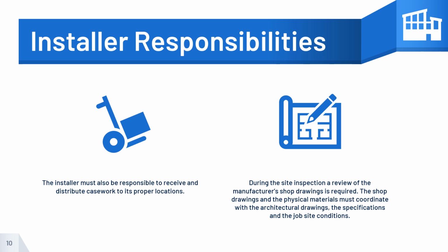The installer must also be responsible to receive and distribute casework to its proper locations. During the site inspection, a review of the manufacturer's shop drawings is required. The shop drawings and the physical materials must coordinate with the architectural drawings, the specifications, and the job site conditions. A few minutes invested at this point in the installation pays big dividends.